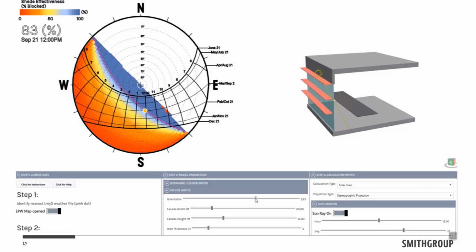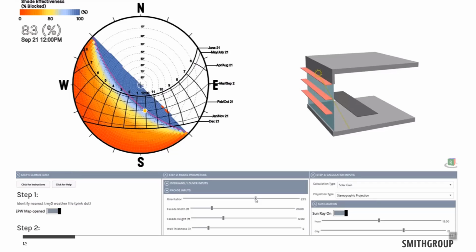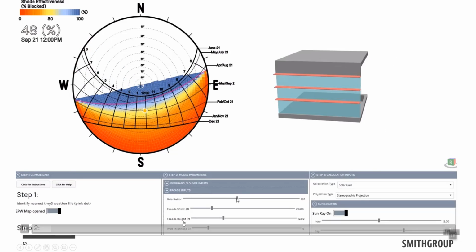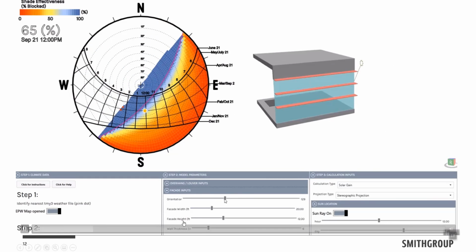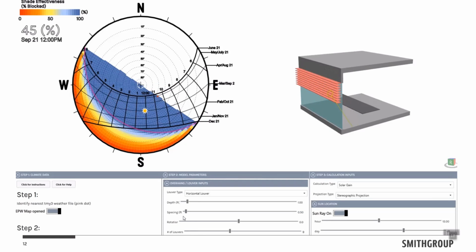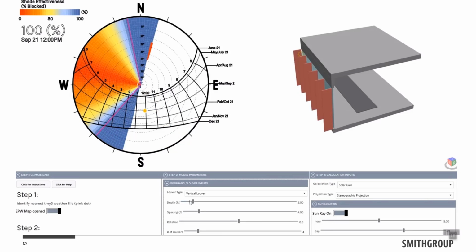So here's an example of that. So right, what am I talking about? Here is an example of a model of a shading system challenge. So rather than modeling a particular exterior shading device as a singular design, instead we modeled all possible shading devices, where, as we go through here, this little tool allows you to adjust, say, the orientation, that's one parameter. Maybe it's the depth of the shades. Is it an overhang? Is it vertical louvers, horizontal louvers? What's the rotation, the spacing? These are all different design decisions we can make.